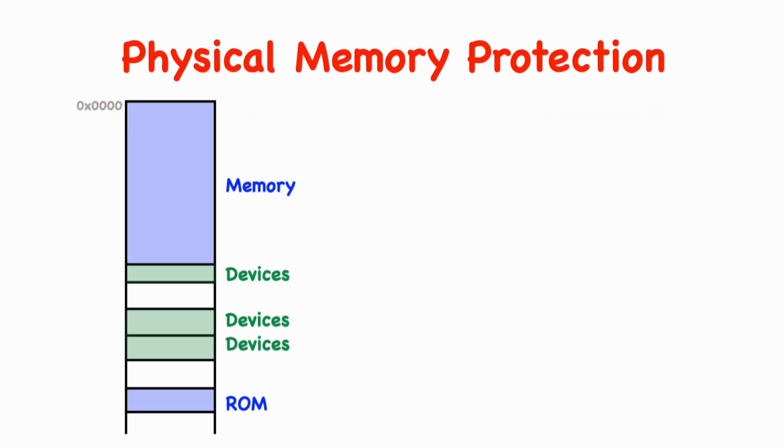The hardware platform will have some physical address layout, as shown in this example here. Some addresses will correspond and map to main memory, and it's likely that there's also a region of read-only memory, which would be used for booting, that's mapped into some other location in the physical address space. And we'll have several I/O devices. In RISC-V, all devices are memory mapped, so each device is accessed by reading and writing to specific locations in the physical address space using the load and store instructions.